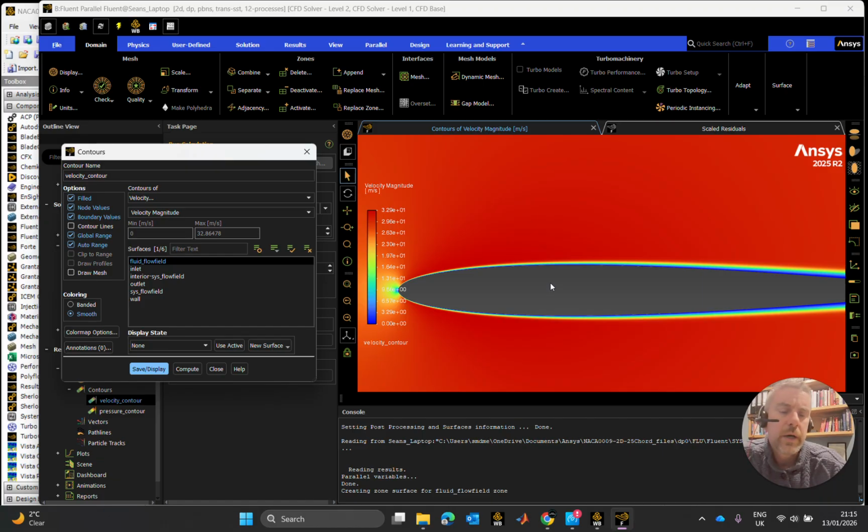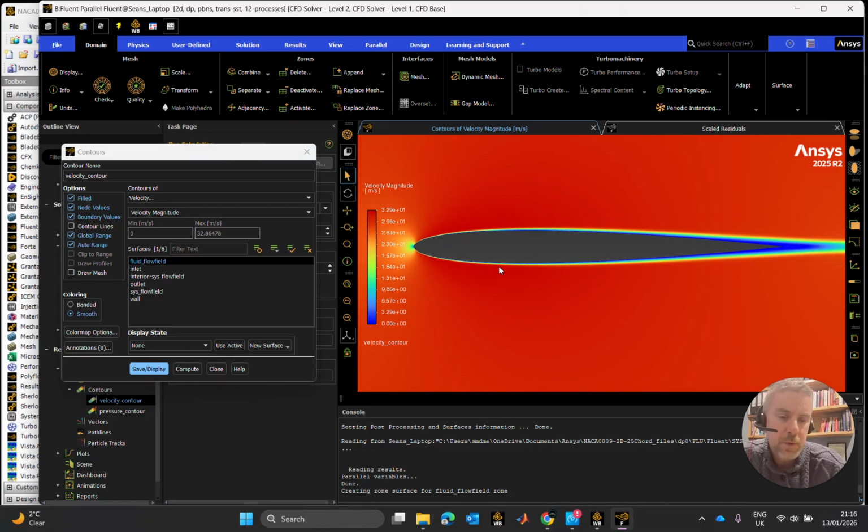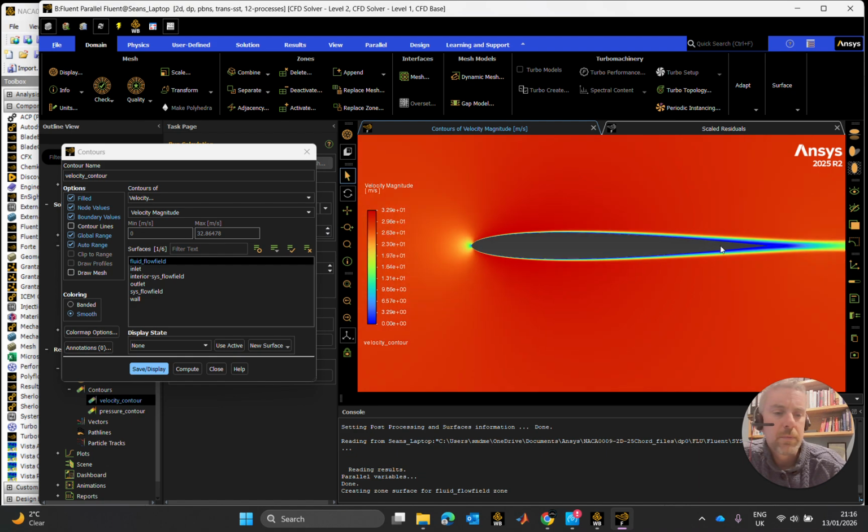But there's also, it can't be forgotten, the classical mechanical element of it as well, the Newtonian effect, which is the momentum shift, the transfer of momentum, which will generally be given by the angle of attack, which will lift up the airfoil, which also has the effect of being responsible for part of the lift.